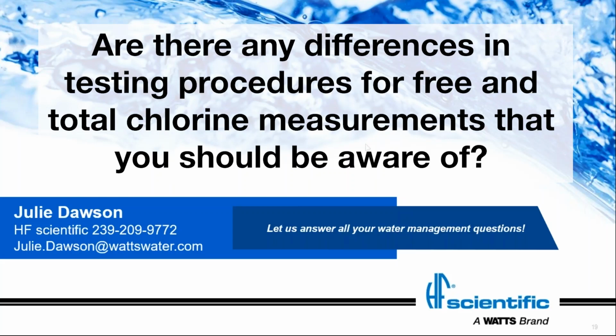For ion selective electrode, we always want to measure the sample within the 15 minutes, but the faster that we can react the sample means less chlorine is coming out of the sample. So once we add the ionic strength adjuster with ion selective electrode, we have complexed the sample, and we want to measure it as quickly as possible always, but less concern than, hey, we've got to measure it right this second. Now, ion selective electrode only measures total chlorine. It doesn't measure free chlorine, so there's not this time period like there is with DPD.